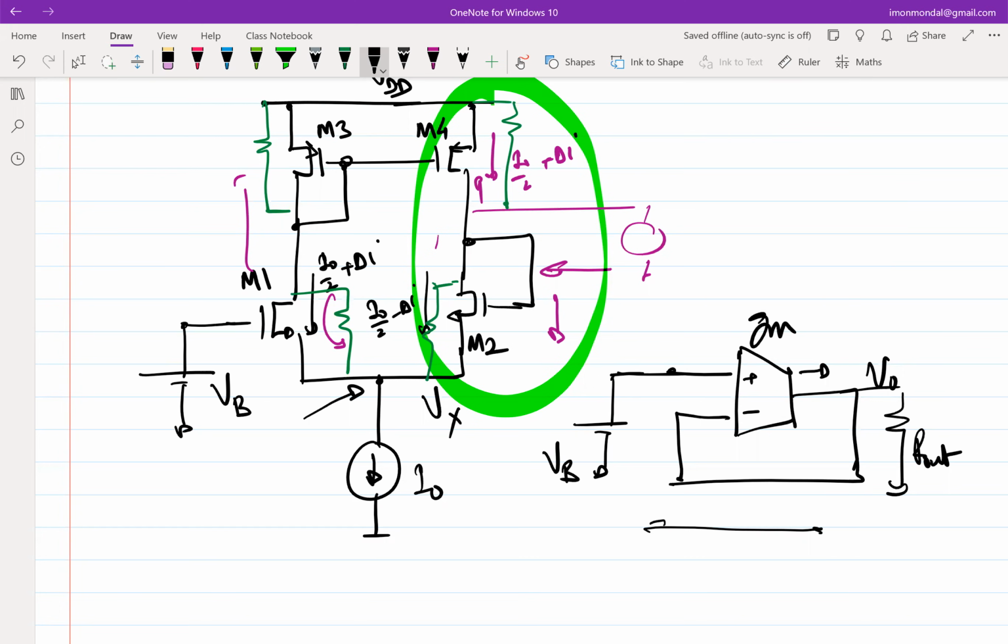Open loop condition of setting all the transistors at the proper operating point, setting all the operating points exactly, and then making the closed loop condition. So that operating point reflects that. The open loop operating point and the closed loop operating point need not be the same. So that's why you don't start off with open loop operating points. You put it in negative feedback and put some high impedance, and then you try to break the loop while keeping the operating points the same, right? Otherwise you are doing two different designs.